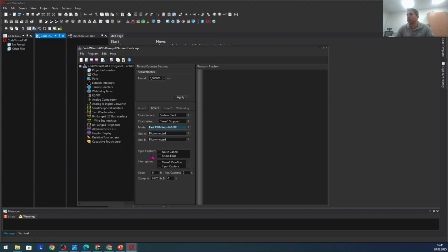So after that, if we connect this to non-inverted, the system clock should be this one. So we had 16.384 milliseconds, and with the setup, the OCR1A, the output compare that we put here, as you can see, is a 16-bit register, so we have to put this. Then we will get a pulse width of 14.7-some milliseconds.